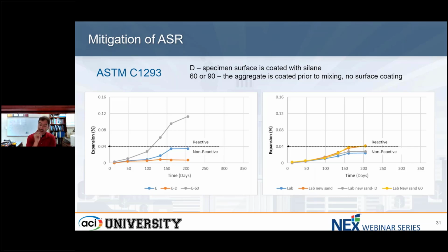So this now is getting into examining the actual chemistry of how silanes behave in highly alkali environments. And when we look at the literature on this, there's essentially none, because most of these silane compounds in the realm of concrete usage are used on the surface. They're not exposed to highly alkali environments for extended periods of time or elevated temperatures. And so the chemistry of this is really not well understood at this time.